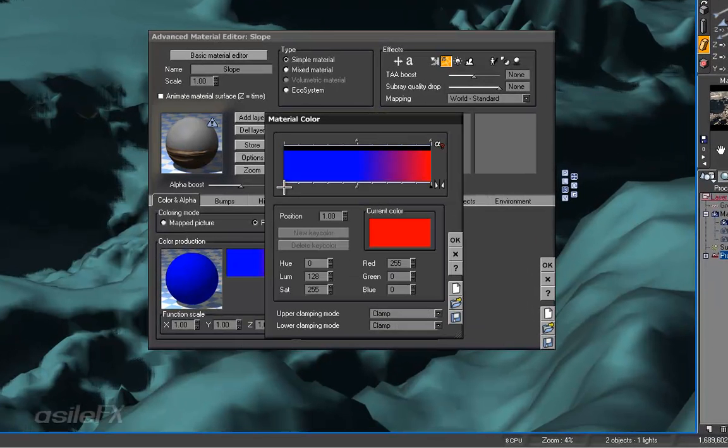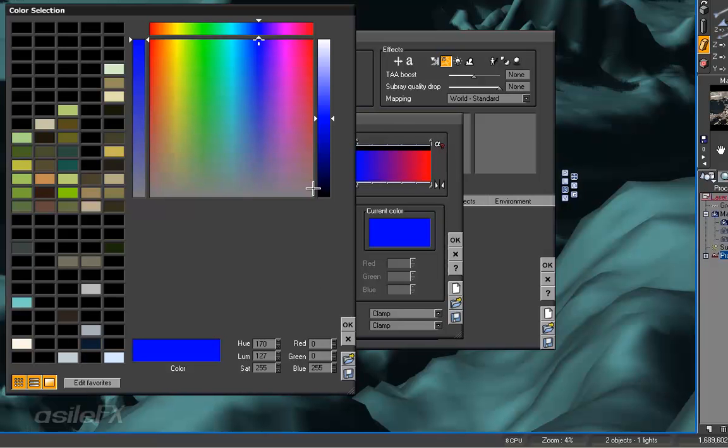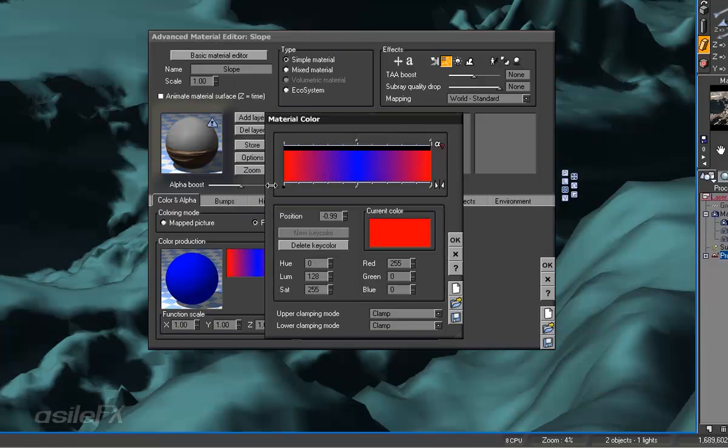So if you want, you can set up a color for the lowest point, which we can also set to red, or you could use green, really anything you want, and set its position to -1. Now if you want to have any in-between colors, you would want to set them up now. This is a layer we'll be able to use over and over again whenever you need to render out slope and really take a look at it. It will be more useful to have an additional key point and an additional color to evaluate the slope.